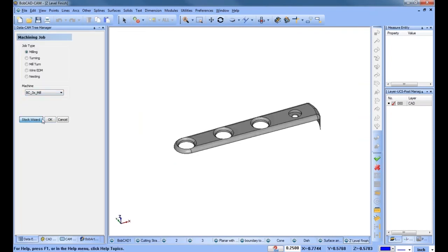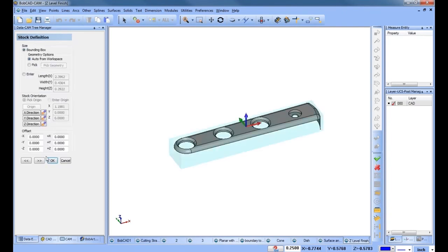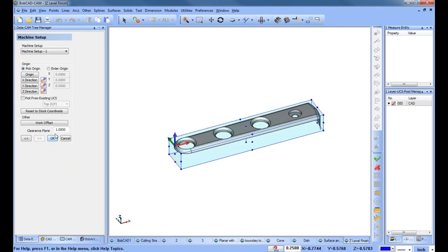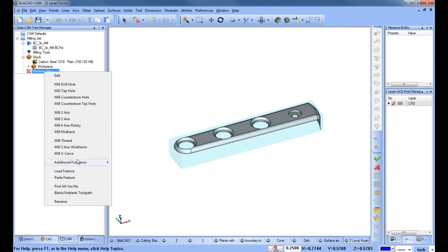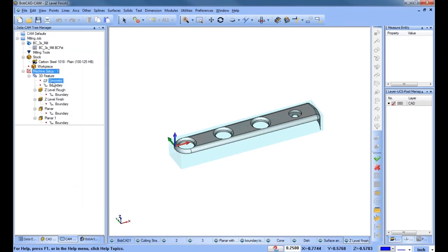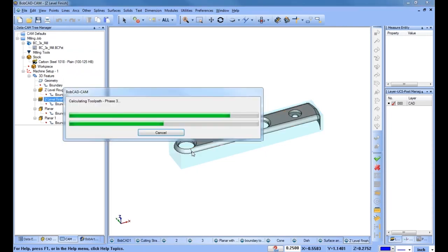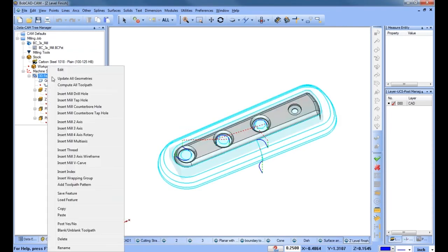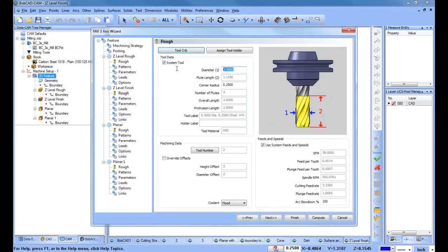This one has to do with fill surfaces, or what I would call a fill surface, where you want to block the toolpath from going down into an area. So if we select all this and we do our Z-level finish and compute this, let's change our tooling a little bit. We'll drop this down.